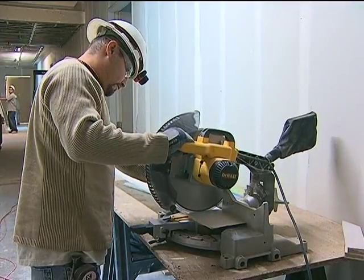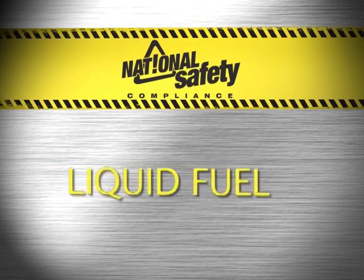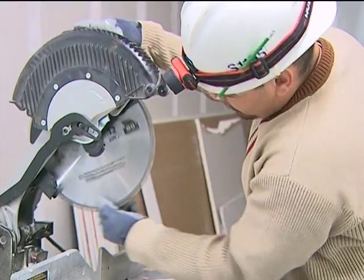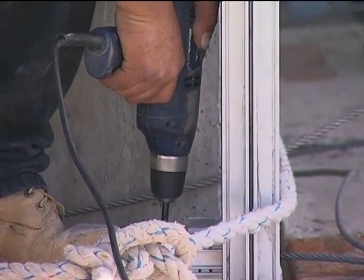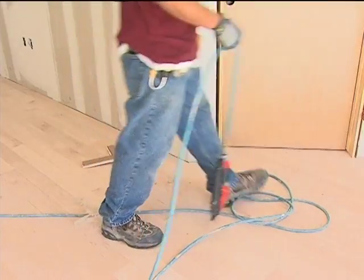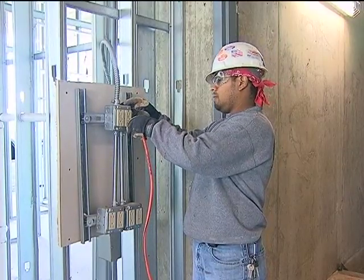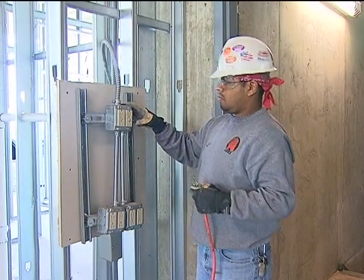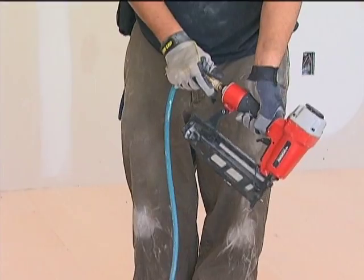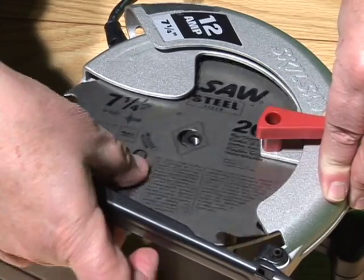Power tools are classified according to their power source: electric, pneumatic, liquid fuel, hydraulic, and powder actuated. Power tools should be fitted with guards and safety switches. Power tools can be extremely dangerous when used improperly. Never carry a tool by its cord or hose. Always disconnect the tool from the receptacle by pulling the plug and not on the cord or hose. Protect cords and hoses from heat, oil, and sharp edges. Disconnect tools when not in use, before servicing and cleaning, and when changing accessories.